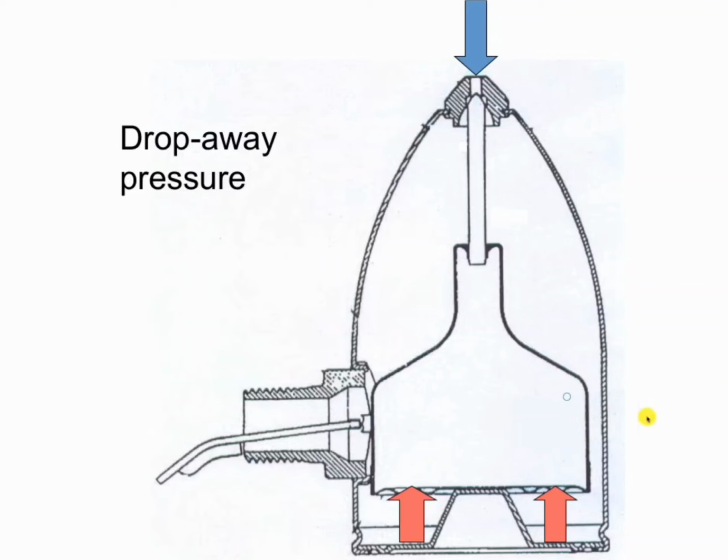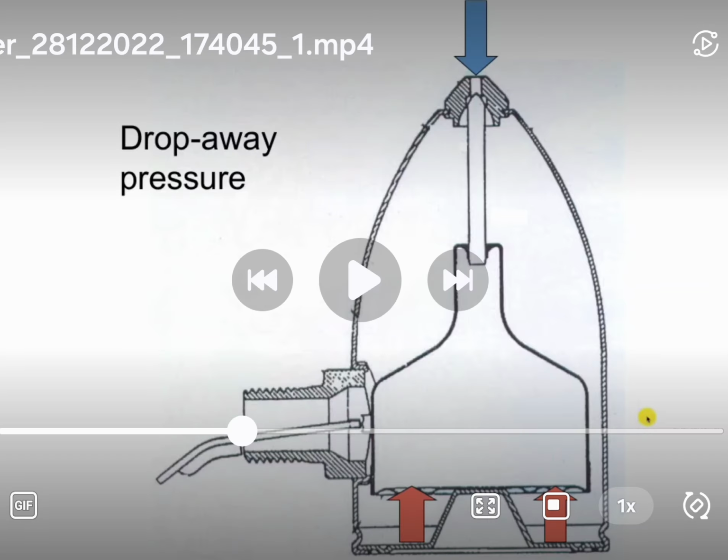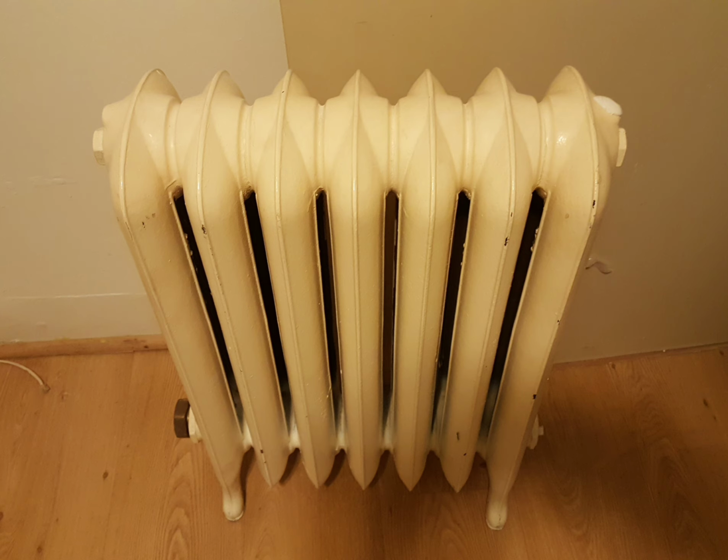And pretty much how this works is, if you're dealing with a cast iron radiator, the larger the radiator, the more air it's going to hold, depending on how the radiator actually heats up. And this is something else, why I tell you people need to understand the personalities of your system. Let me see if I can put forth an example for you. So when we talk about the personalities of heating systems and air vents, that's going to be based off of where this is located in the system.